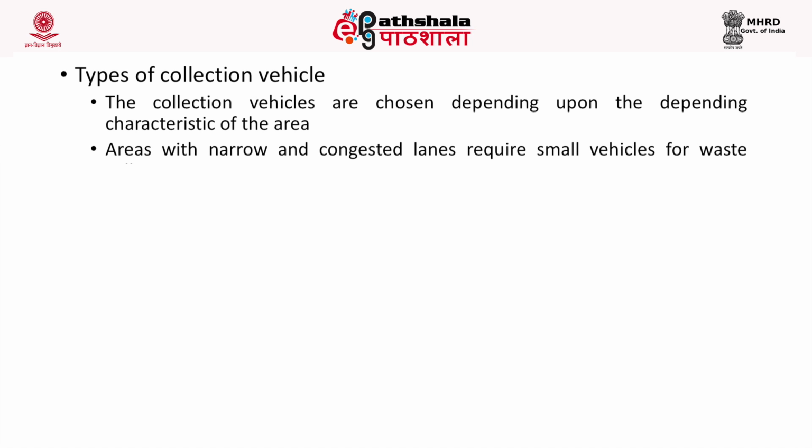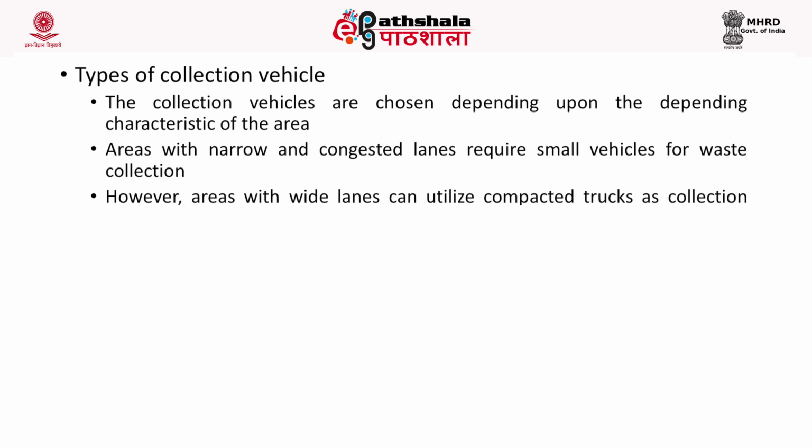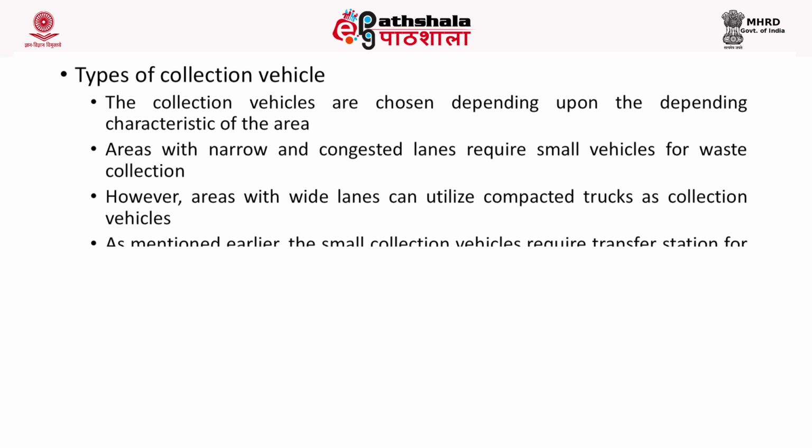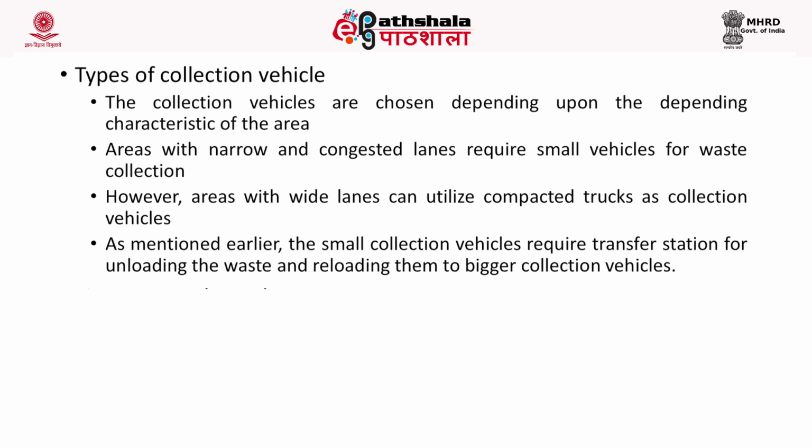Now, based on the type of collection vehicle, in general, the collection vehicles are chosen depending upon the characteristics of the area. If you have narrow and congested lanes, then you go for a small vehicle, and if you have a wide lane, then you use compacted trucks. As mentioned earlier, the small collection vehicles require a transfer station for unloading and reloading them to bigger collection vehicles.